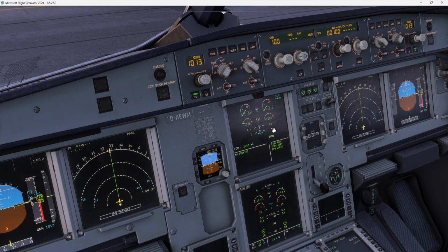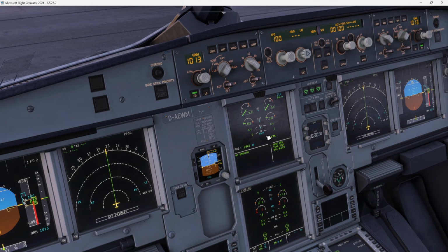Then the FADEC is going to take control. Then we are going to see here the fuel flow, which is kilogram per hour, or in some planes we measure it in pounds per hour, and it is going to inject fuel. And there we need to see that the N1 is rising. If it is not, we abort the start, because we have a limit. Also as the fuel flow is injected and the N1 is rising, the oil pressure is rising too.